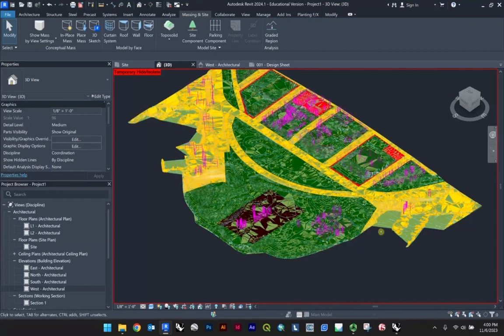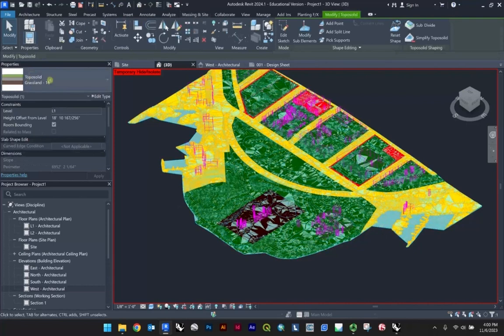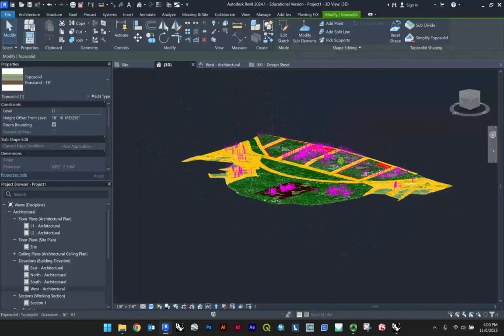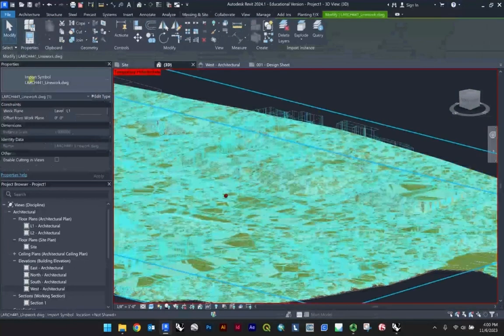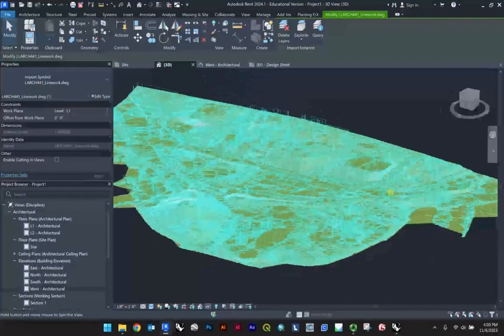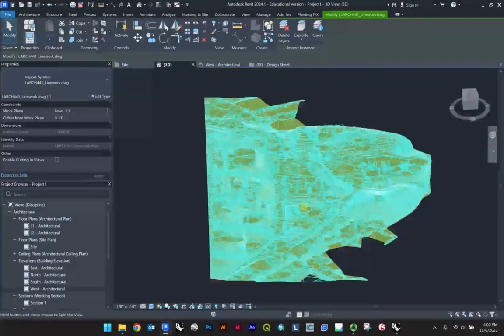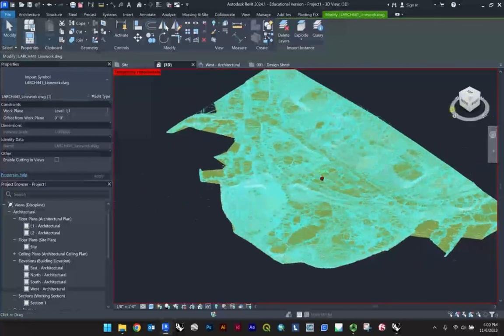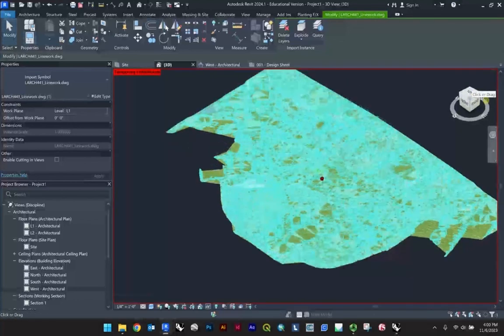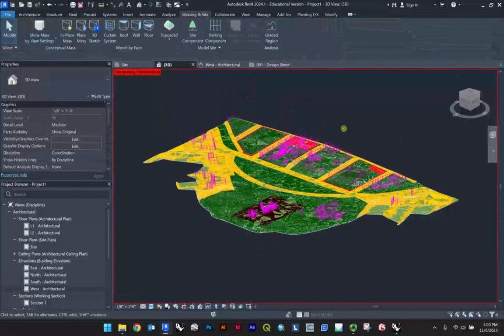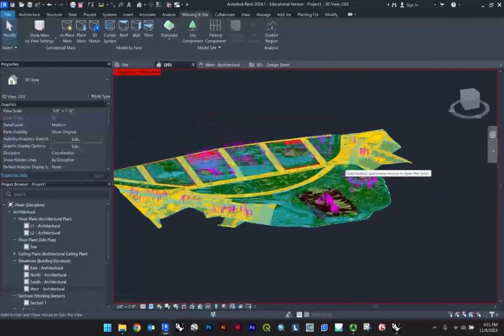So what you'll see here now is we have this new topo solid, and we do still have our overall, let me just orbit around a little bit. We still do have our imported symbol. The way I'm orbiting, by the way, you're holding shift and your control wheel down. So that's how you're actually orbiting around in 3D space. You could also just click on this, which is the same kind of toggle thing as for, say, the 3D interface for even AutoCAD. I would say shift and control wheel does work quite a bit nicer for us.